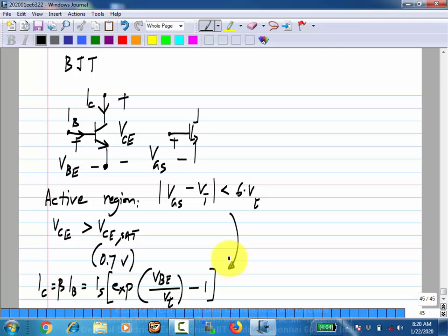In a real MOSFET, according to the 0th order model, if VGS is less than VT, the current is 0. That doesn't happen. Actually, when VGS approaches VT, the current starts falling exponentially but it won't fall to 0. So in this case, basically,